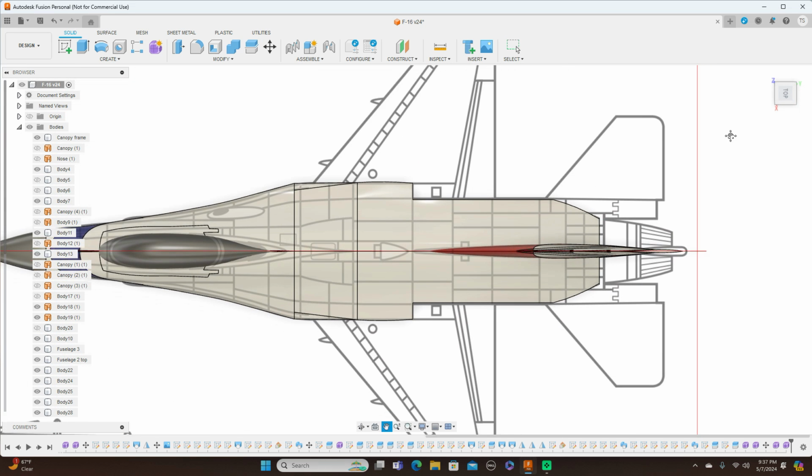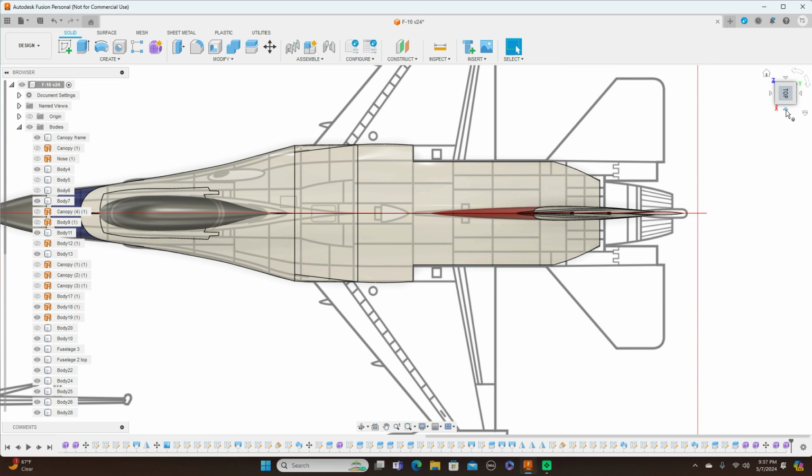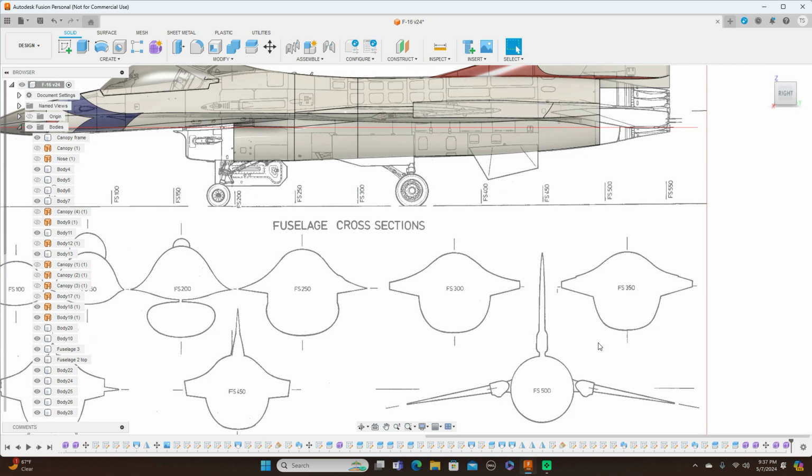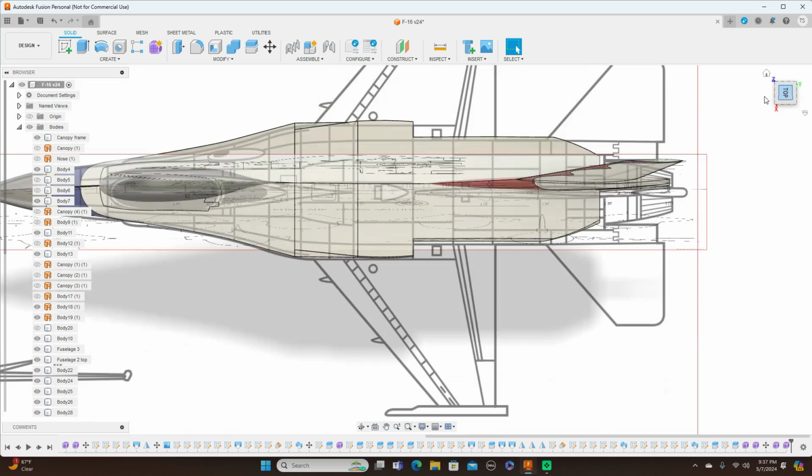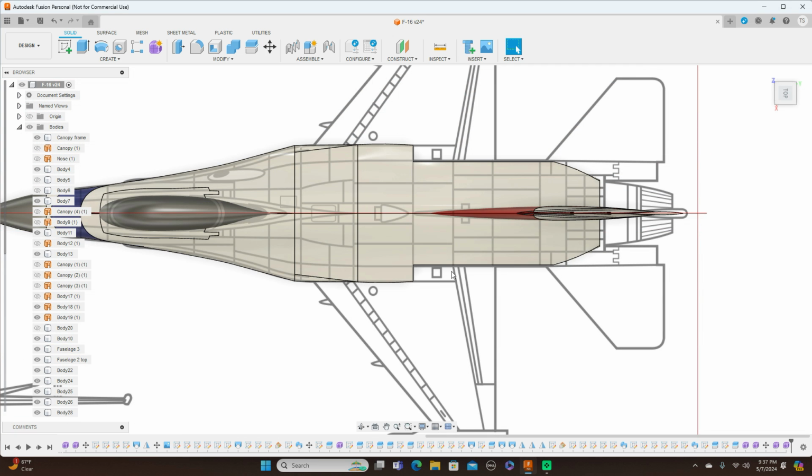And what I did also, these shapes are a lot longer on the outside than this one. So when you loft that, it creates an arc back to that former, and you don't want that arc there. So what I just did is, let me turn on the sketches and show you.